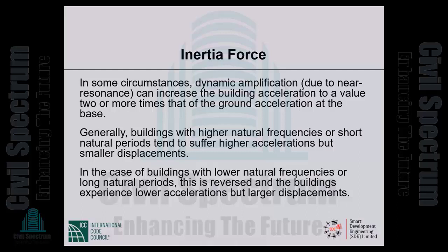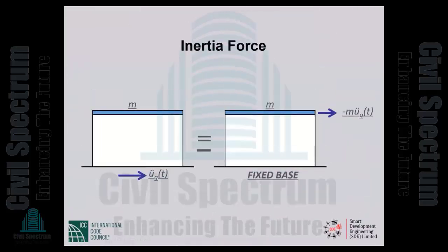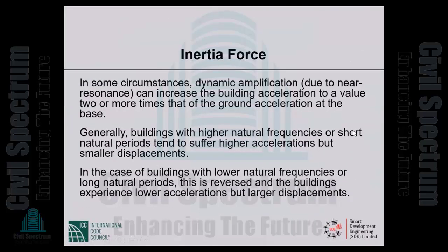In those cases, the dynamic amplification can increase the building acceleration to a value 2 or more times that of the ground acceleration at the base. So the acceleration, particularly for taller buildings as you go up, can be many times U sub G double dot. It's not necessarily equal.